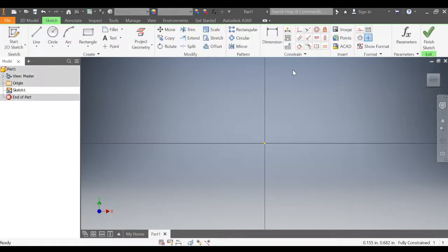And this is going to bring up our drawing options, our sketch options, and all this. Think of this as a coordinate grid, okay? This right here is the origin. This is your 0, 0 point. You want to start your sketches on the origin point. That is best practices right there. Start them on the origin and it will ground them there.